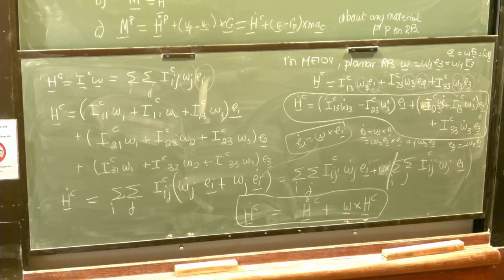For example, if you have a washing machine, it's rotating, right? If the clothes are evenly distributed on the rim of the washing machine, it will rotate about the axis of rotation. The center of mass of the clothes is at the axis of rotation, it's going to rotate, no problem, right? If I put a bulky item in there, the mass is not evenly distributed. So the center of mass is off center from the center axis of rotation. The products of inertia are non-zero.